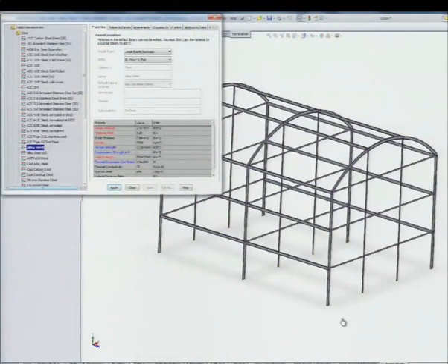Do you apply the load only on the vertical? No, I will apply the load on the columns that are the structural members in charge of taking the horizontal force, and I will apply the load on the curved beam. Yes, the lifting load. In this way, no, but of course that is called another load case or load environment, right? Because you have to take into account the weight of the wind. Yes.